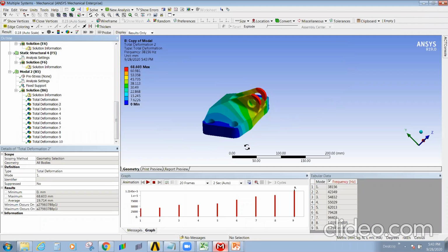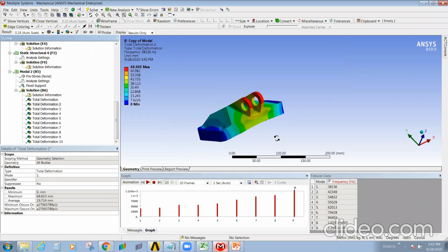See, deformation is for self-excitement. It is like you're doing an experiment with your tuning fork or your pendulum. You're giving initial excitement, your body is moving, and with respect to time you take into account how many oscillations it is taking. Similarly, your software will apply a self-excitement and solve for that. Your displacement values are the magnitude of your pendulum with self-excitement. So that is what is mentioned.